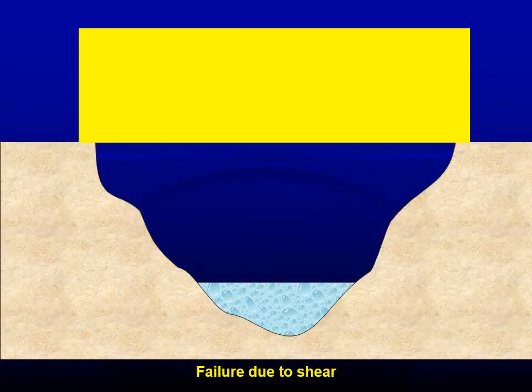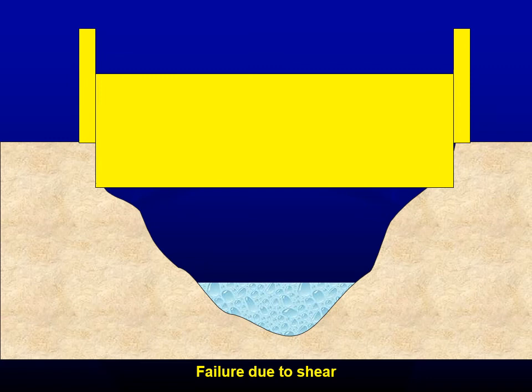So when your bridge is placed, it will be supported on either end and will be loaded in the middle. And those points where the loading is are the most important points that need to be reinforced. So where it's supported, you can experience a force called shearing. This is a vertical force where the one point is pushing up and the other point is pushing down, and it wants to rip itself away from itself.